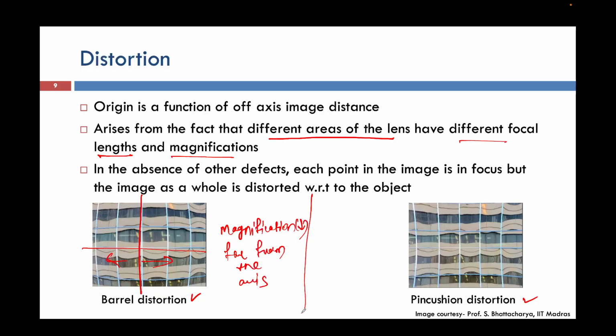You can imagine a cylindrical shape that starts to grow isotropically. Let's say this is the original shape and I am applying some load P here, and what will happen? It will bulge like this. So this is known as barreling.